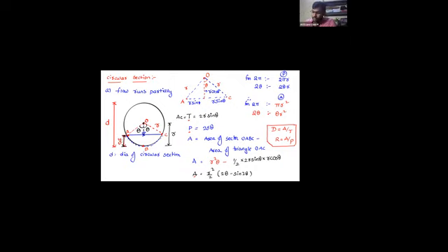So now, what is the depth of flow? Listen to me, can I write the depth of flow y is equal to, what is the total depth from the center to the bottom point? r. And what is this vertical ordinate? This vertical ordinate is going to be r cos theta. So can I write y is nothing but total r minus r cos theta.